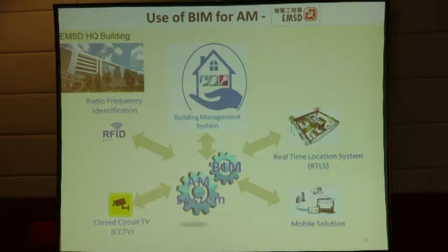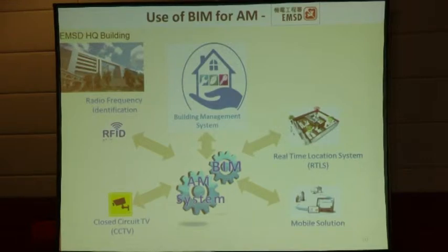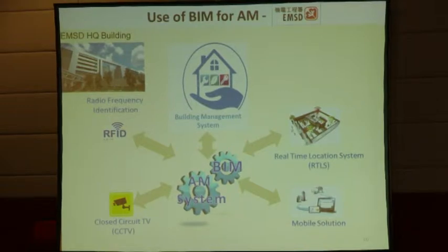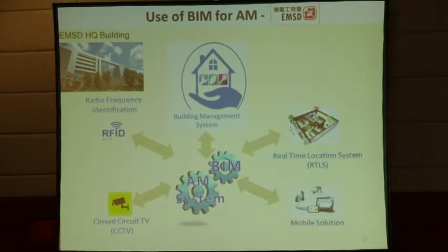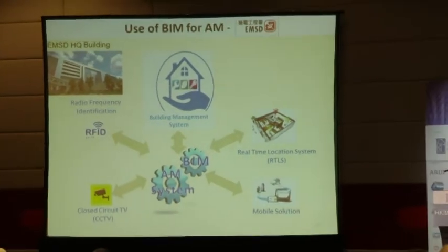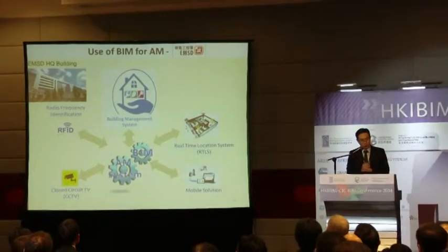In the process of their model development, the project team carefully considered user requirements of the BIM AM system, as we call it, with a view to bringing the most benefit for operation and maintenance. The BIM AM system will interface with their existing building management system and other new electronic systems and technologies, such as RFID, CCTV, real-time location system, and other mobile solutions.